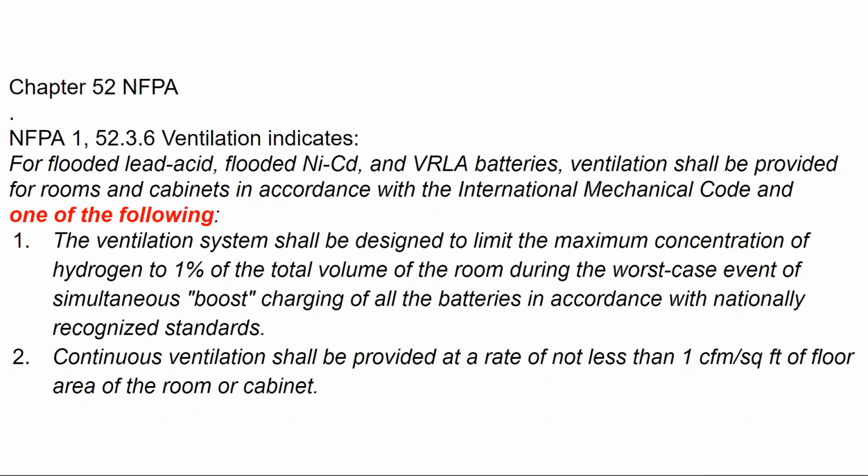So, having a hood over the batteries that gives the lightweight gas the ability to vent to the outside on its own, but putting a small fan inside the tube to turn on when the battery is under heavy use, or you're going through your maintenance charges by pushing that battery all the way up to the very top of its voltage. Ventilating during those times is the way to go.